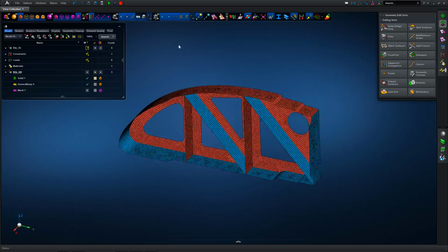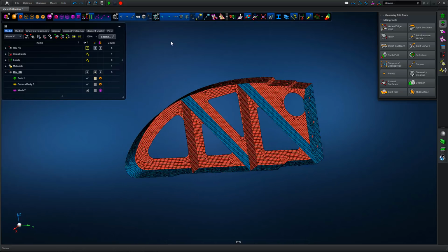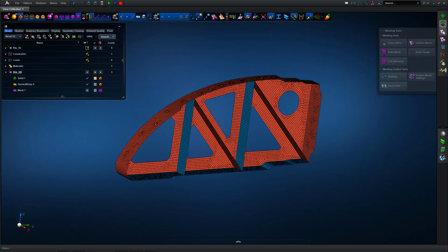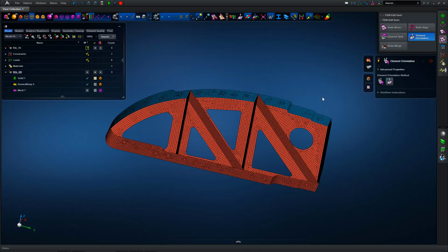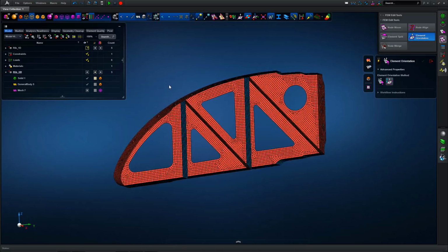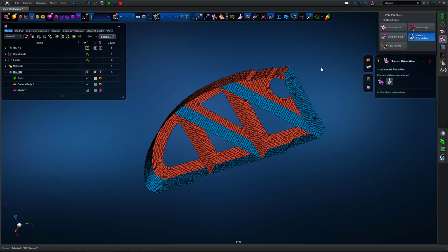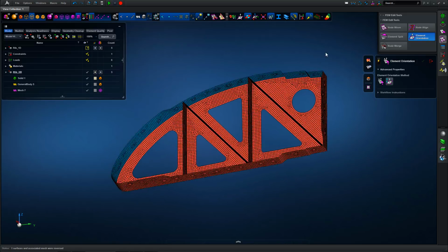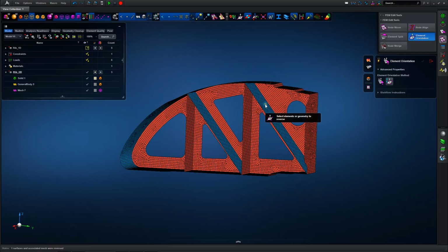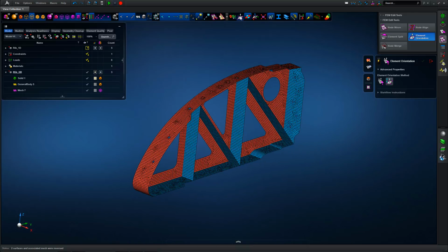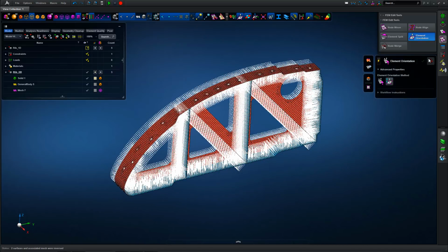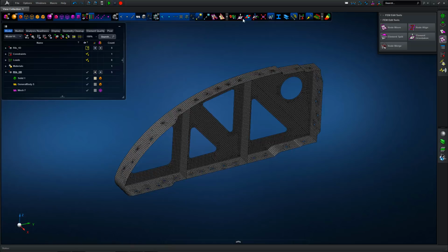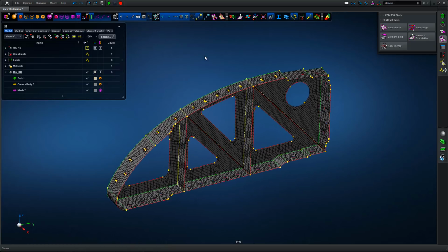and the rest are dominated by good quality elements. So a check on surface normal consistency, again colour coding the upper and lower face of the shell element, so we can see some of the areas are pointing in a direction we're perhaps not happy with in terms of consistency. So we're just going to pick an element in that given meshed region, and it will automatically flip the connected shells to suit. So we can now see we've got the shell normals consistent first of all, and then the orientation is highlighted as a vector plot, so we can demonstrate that we're happy with that.